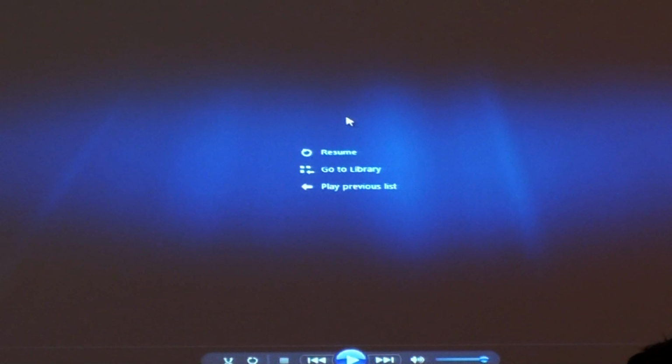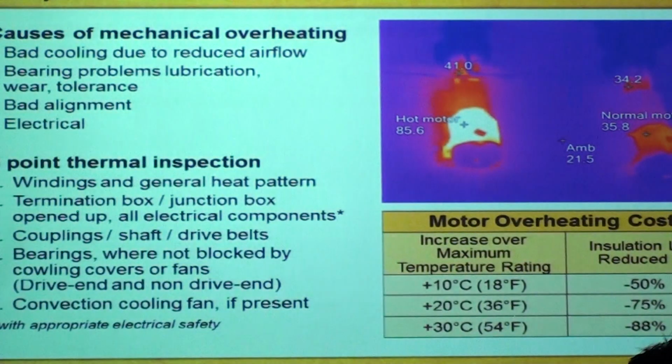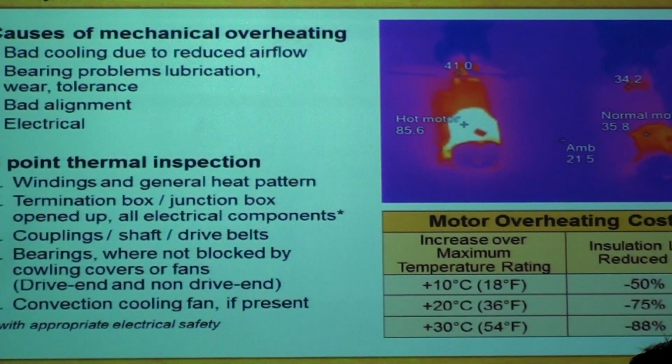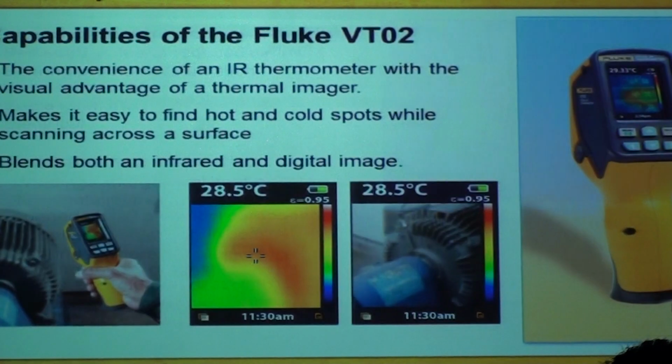Okay. So, nice little video to show you a typical 5-point thermal inspection. And again, like Michael clearly says in the video, sometimes you need more than one tool to do it. So if you have overall heating on the motor, you might want to install a power quality tool to see what's wrong. If the camera is showing you bad alignment, you want to verify that by using a vibration tester as well. But thermal imaging is a very easy tool to use. It's quick and intuitive, and it gives you an answer on the spot.